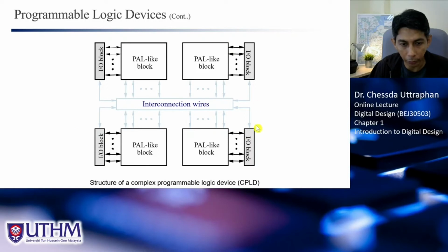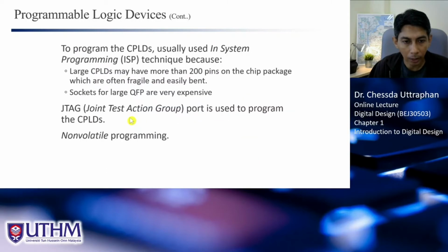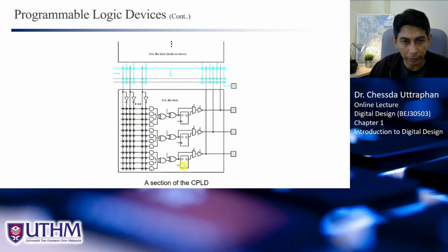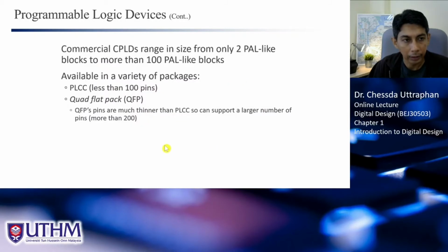This is the view of the CPLD, where you have many PAL-like blocks connected together, which means that you can create a more complicated circuit using a CPLD, because you have more logic blocks available, right? So this is what is inside the CPLD. Actually, this is the PAL-like block. So this is a PAL actually, and this is the output pin.